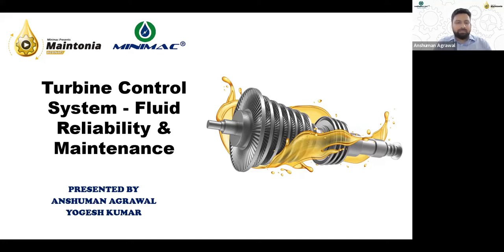However, if we consider the properties of this fluid, in most of the cases, like 90% of modern turbines, this fluid is of fire resistant nature. That's the reason why it is also known as a fire resistant fluid. The chemistry of this fluid in most of the cases is ester based chemistry. It can be a phosphate ester or a polyol ester. That's why many times people also say that it's a phosphate ester fluid.